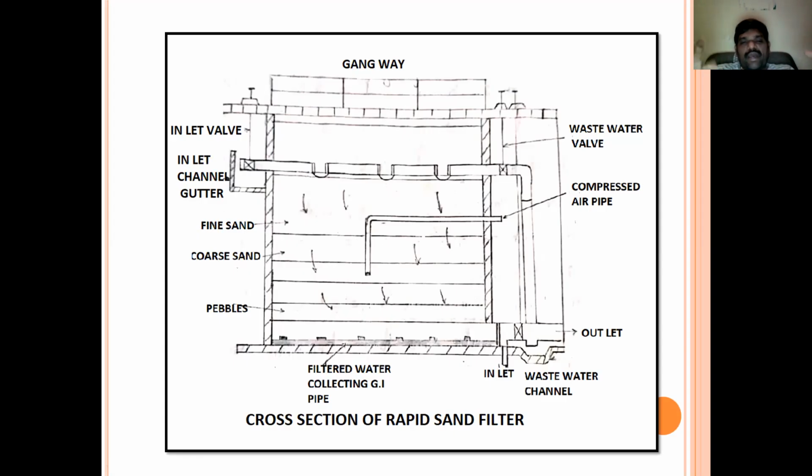By doing so, the voids in between the sand granules will be released, and the dust particles in the voids will associate with water, and the water which contains the material blocked in the voids can be taken off through outlets.